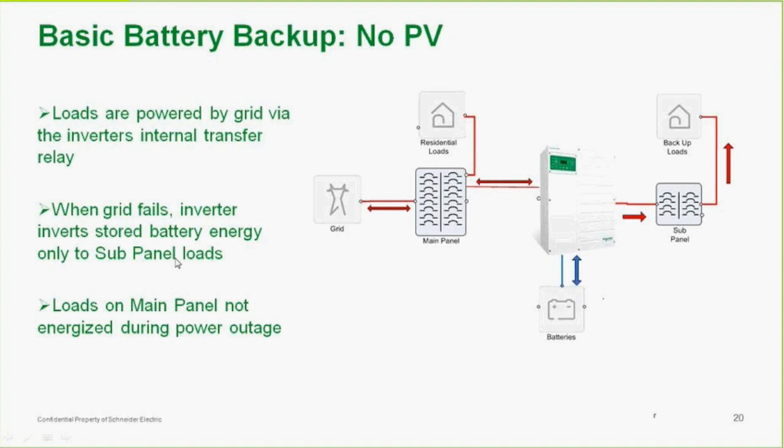And one of the things that people try to get around, and I understand it, is that one of the most complicated parts of doing a battery backup grid tie system, in any home and from any inverter manufacturer, is the fact that you have to pull this sub-panel. But keep in mind something. We didn't talk about that transfer switch in much detail earlier, but that transfer switch is rated at 60 amps, 48 continuous. So if you were to put this inverter upstream of the main panel and try to feed the whole house, you would have a bottleneck.